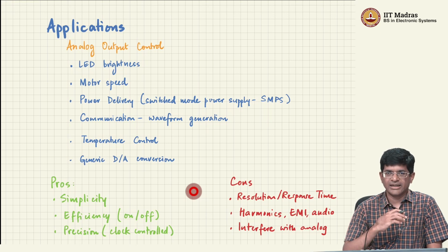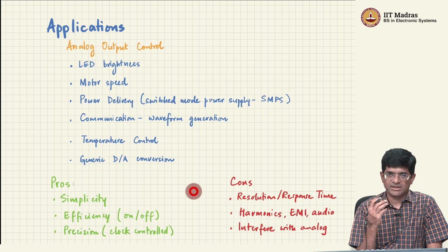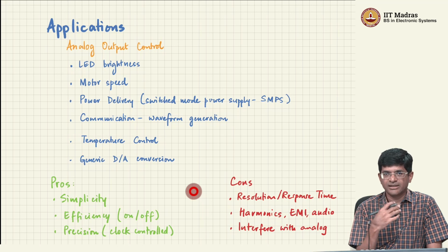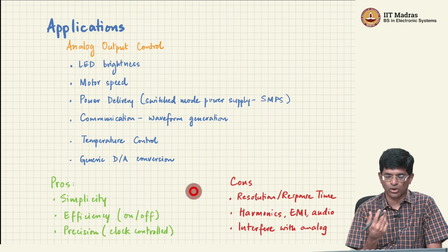So LEDs, unlike incandescent light bulbs, the ones with tungsten filaments, just by increasing the current through it, the variation in brightness is a second order effect. It is not directly proportional to the amount of current, and in fact increasing the voltage and hence the current through the LED is usually a bad idea, because they have a very sharp variation with voltage, which means you can easily damage the LED if you send too much current through it without getting the benefits in brightness that you would like to see.